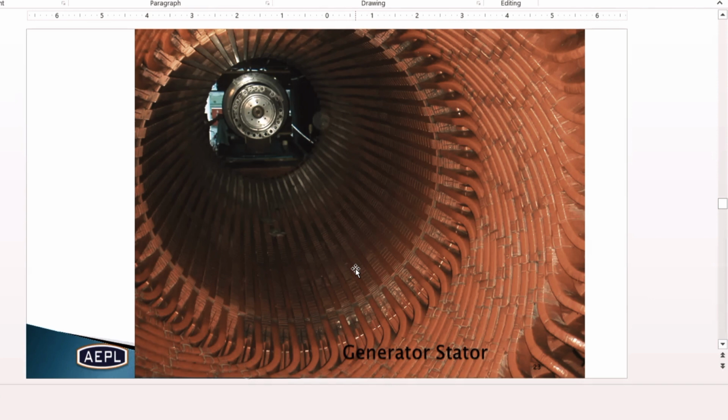Short circuiting between these two conductors of the different phases, because the same voltage is appearing, also the 20 kV of voltage inside the slot. In between the slots, the insulation strength is very high. But if there is any leakage or the insulation has become damaged, inside the slot these two conductors may pass the current. It means that the differential relay will operate in that case, right?